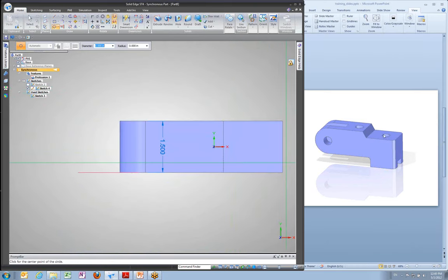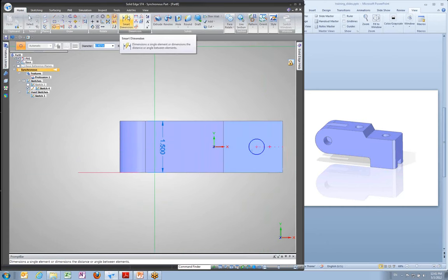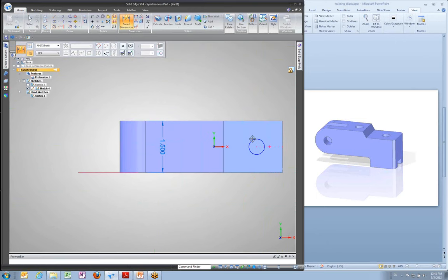So I'm going to create this hole cutout here, and I'm going to do that just by drawing a circle in here. And the first thing I'm going to do, I'm just going to mouse over and wake up that midpoint so that when I come over, I'm in line with the center of that. And I'll click once to place that hole. Now maybe some dimensions to finish this off. I want to drop this in here, and let's say we want to make it a 3/8 hole. So I'm going to go 3/8, just like you would in an Excel sheet, and hit enter.